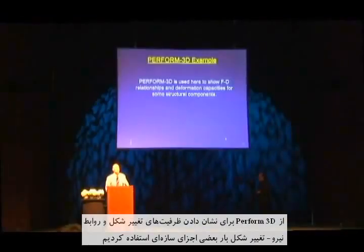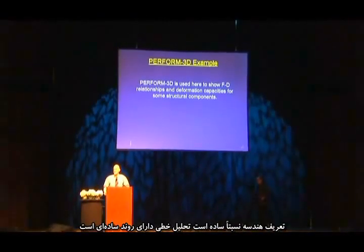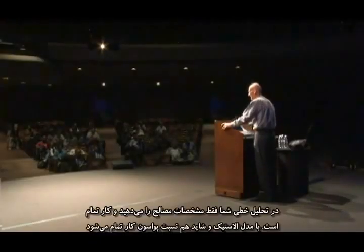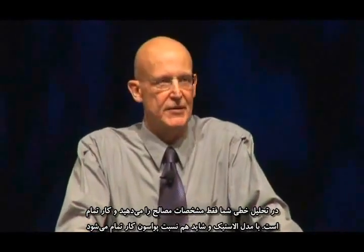So we just did that, and we used Perform 3D to show deformation capacities and force-deformation relationships from structural components. When you're building a model, most of your time is going to be spent in that component properties portion of the input. Defining the geometry is relatively simple. Defining the nonlinear component properties is far from simple. In a linear analysis, it's a simple process. You just give it material properties, you're done. Elastic modulus, maybe a Poisson's ratio, that's it, you're done.